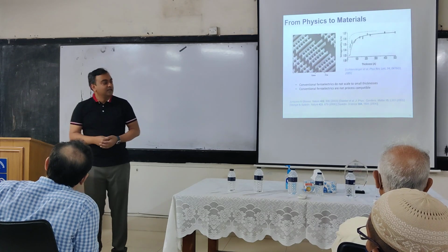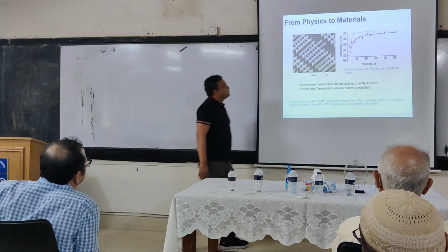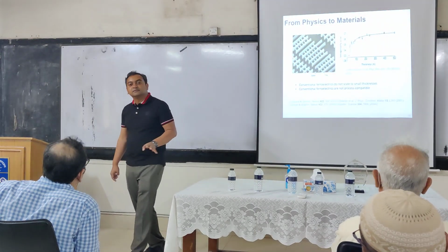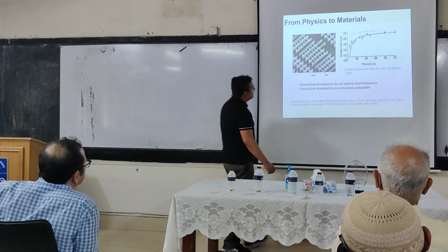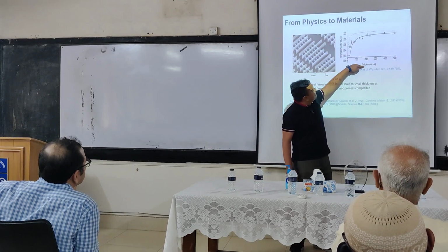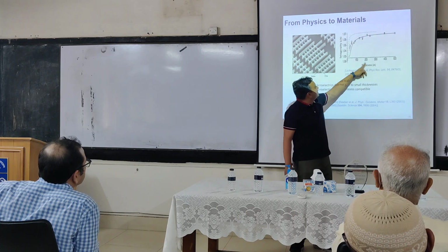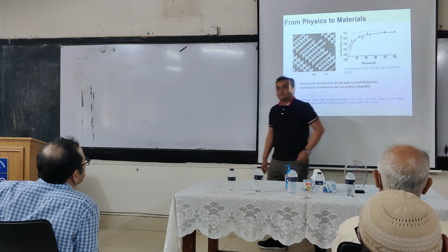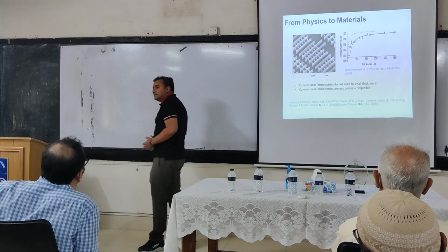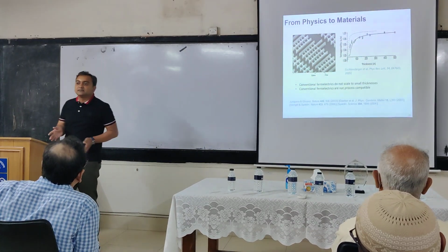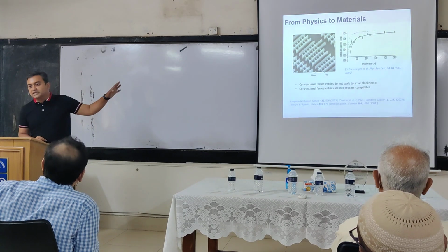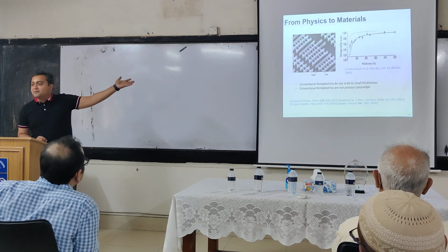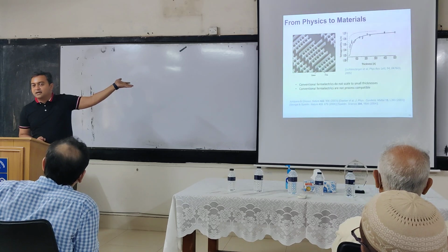It's a big problem. So when we started working on ferroelectrics, people said, yeah, you are doing very good fundamental work, but it's absolutely useless. Why? Because for conventional ferroelectrics, it is known that when the thickness is in angstroms, which is 1/10 of a nanometer, by the time you are below 10 nanometers, ferroelectricity goes away. So they said, I don't have the space for a 10 nanometer ferroelectric inside my fins. There's no space. You are doing great physics, but I cannot use it. The conventional ferroelectrics are not usable.